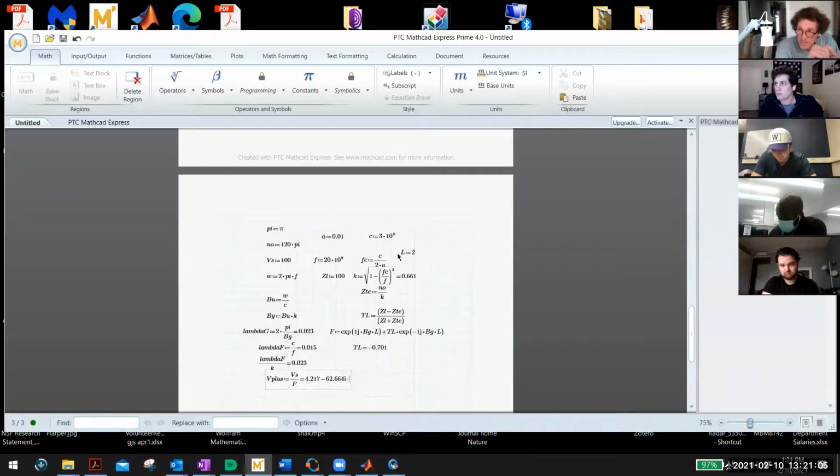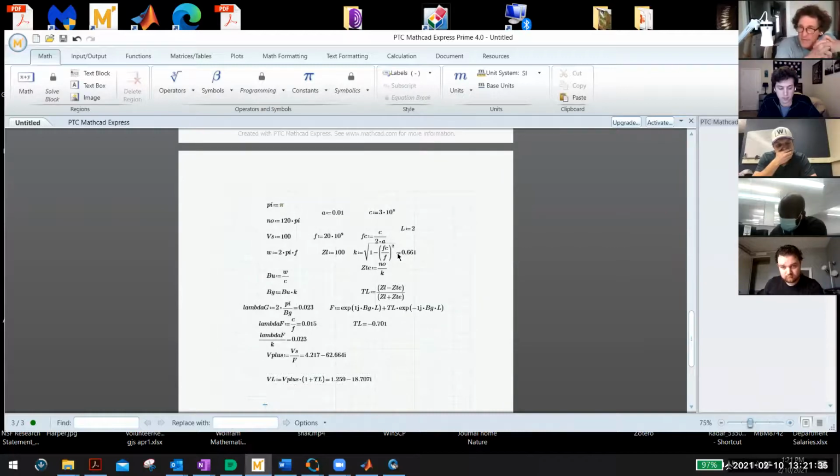You with me? Now, how much voltage goes to the load? This is the voltage at the load. Well, that's V plus, right? Do you remember what I do now? I multiply it by, anyone? 1 plus the reflection coefficient, right? And that's what I get. You'll notice that's complex. Everybody? That doesn't matter. You care only about the magnitude. Now, my load is strictly real, correct?